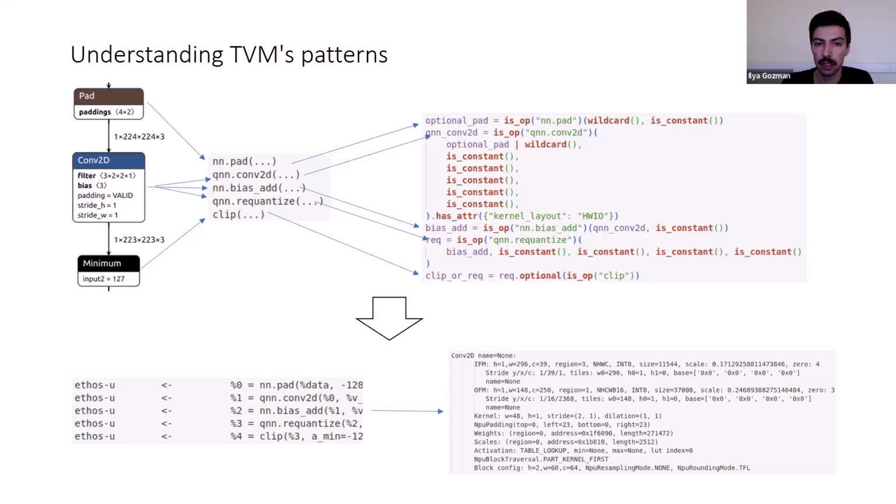What we need to solve this is a relay. First, we need to dissect relay and understand what can be optimized. However, an operation won't be represented by just a single line. For instance, a convolution consists of the convolution itself, an offset or bias, requantization operation, and they can be optionally paired with padding before the operation, or an activation function with clipping. To combat this, we will use a pattern when we need to obtain the parameters of the operation and ensure it meets the hardware limitations. Only after that, we will convert it into one or more ARM Vela API calls.